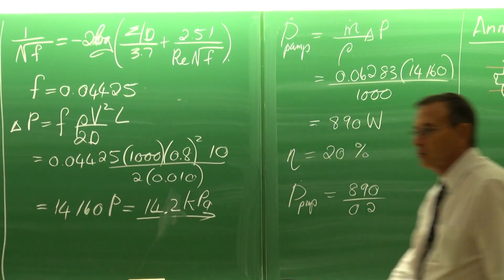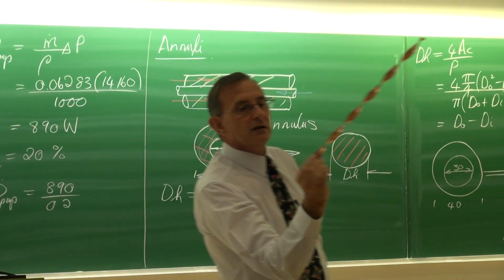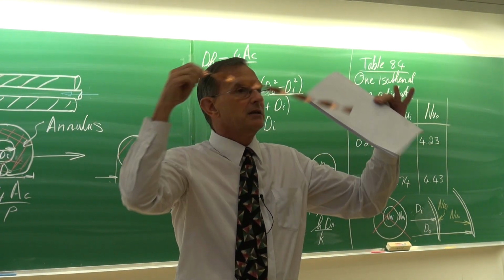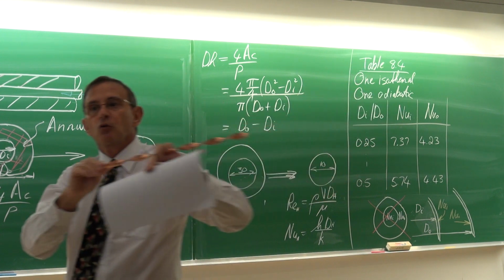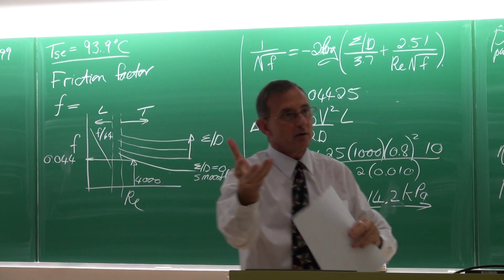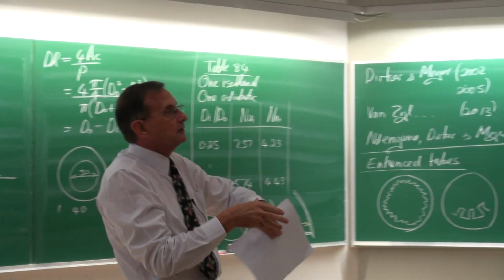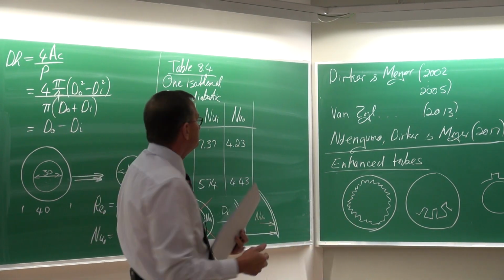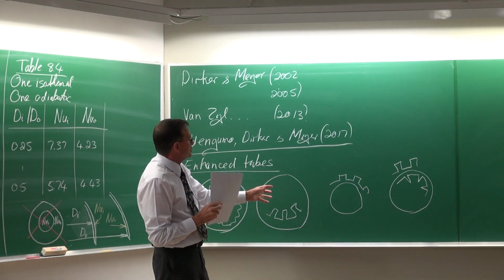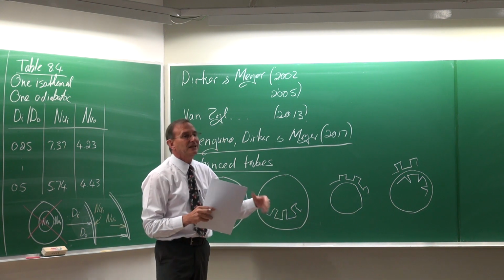One of the simplest ways of doing enhanced heat transfer is to take just a piece of flat plate and just twist it like this. You see? Then you put it inside a tube. What would you do? It would of course rotate the flow. It would spiral it, and that would increase the flow path. Makes it longer and would increase the levels of turbulence. Here the same. All of them would do different types of things to the fluid. The other thing that it does, it actually increases the heat transfer area.